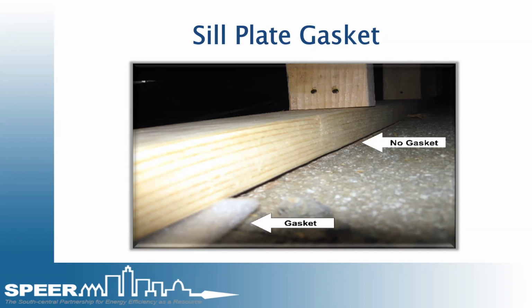A lot of times garages are not looked at as exterior walls. They're looked at as an interior and/or a garage separating wall, but that wall should always be handled as an exterior wall. When it comes to energy, it should be looked at as an exterior wall and handled properly with a proper air barrier and a gasket sealing the base plate.